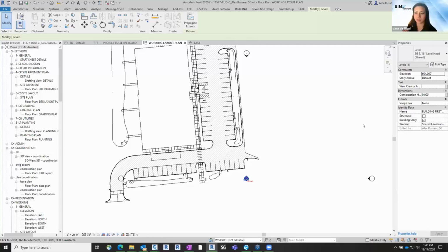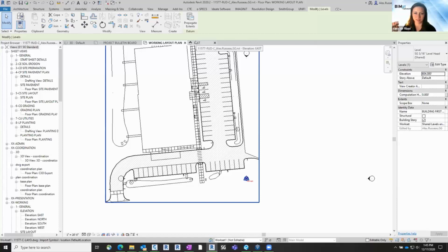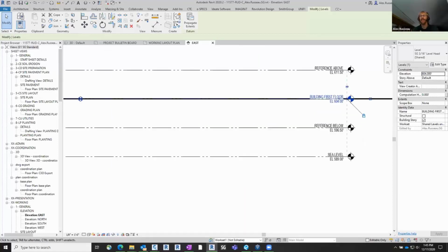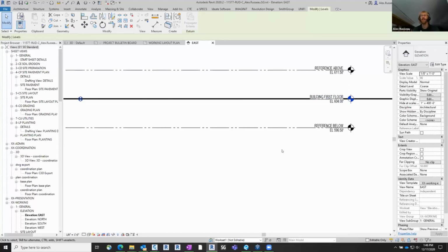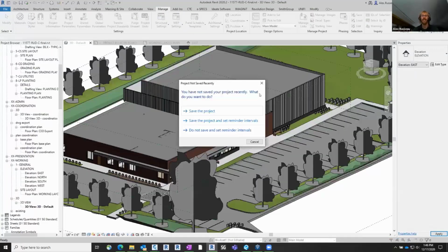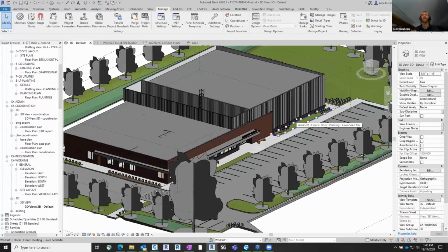And Heather asks, it looked like before you relocated your project using the position tool, your sea level was set to -15 feet. Is that just the way our template, like what? Yeah, that's just the way our template's set up because our building floor is where I really want the building to come in. So I had that initially set at 0. The step that I do next, after I have that first floor set, is I bring this down to 0. And then I do all of my modeling off a survey point or the sea level. So in this beautiful model over here, I end up setting all my floors and everything to sea level so I can type in true elevations to get it all set up.